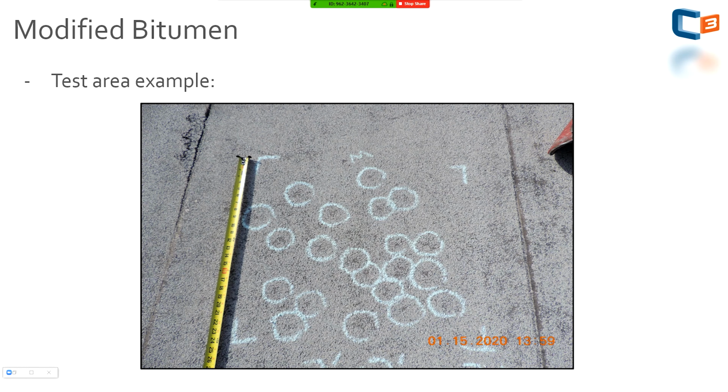So when we flip this over, we want to see basically what this did to the cap sheet. Is this just granule loss? Is it just damage to a fluid-applied coating? And we can determine that by doing a cutout. So in this case, we did a little bit of smaller cutout because these were kind of sporadic on the roof system. This is a smooth roll mod bit cap sheet, so it has an aluminum coating on it.